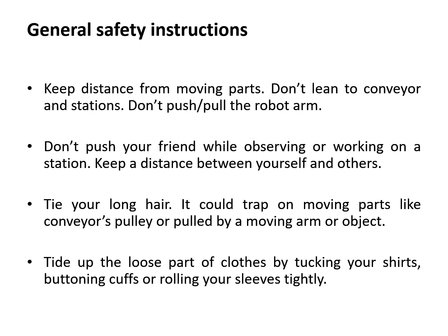General safety instructions, not just in the intelligent manufacturing lab, but in any industrial environment. You should be either the operator or the instructor on how to use that machine, or you should keep distance from moving parts, and don't lean on conveyors and stations and moving parts.